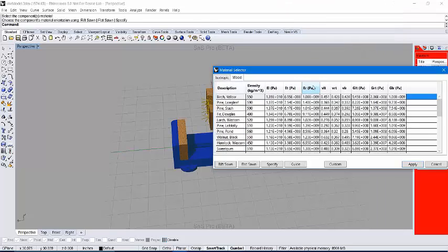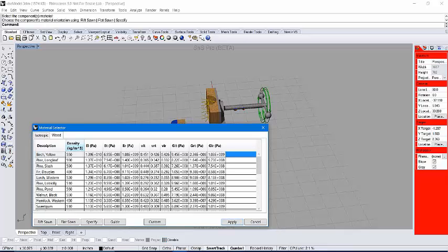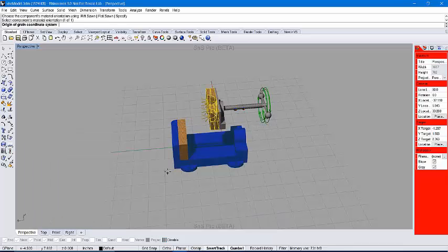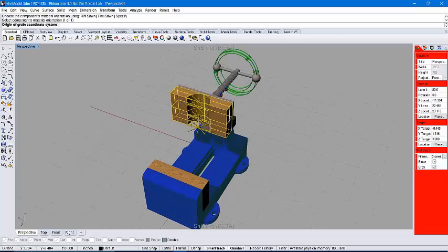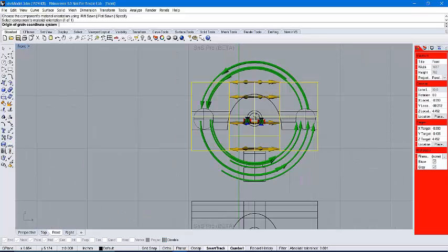we made this yellow birch. There's this specify option, which I didn't describe in detail at all. And what this is, it allows you to customize your own wood grain. So let me hop into a new view. That perspective can kind of get a little tricky when specifying your directions. So it asks you to choose your long grain direction, which is your longitudinal grain direction. So I'll just throw that in at an angle. And your radial grain direction, and I'll throw that down here. And it will compute the tangential from this information. So I'll hit apply.